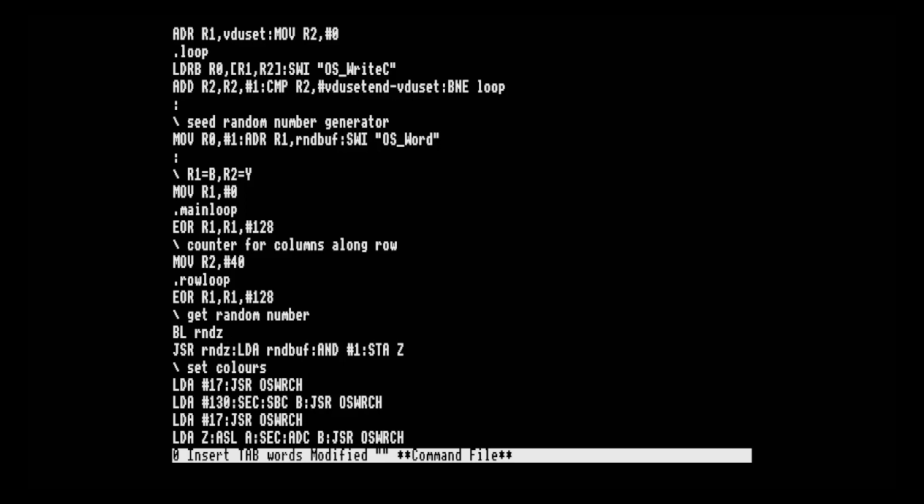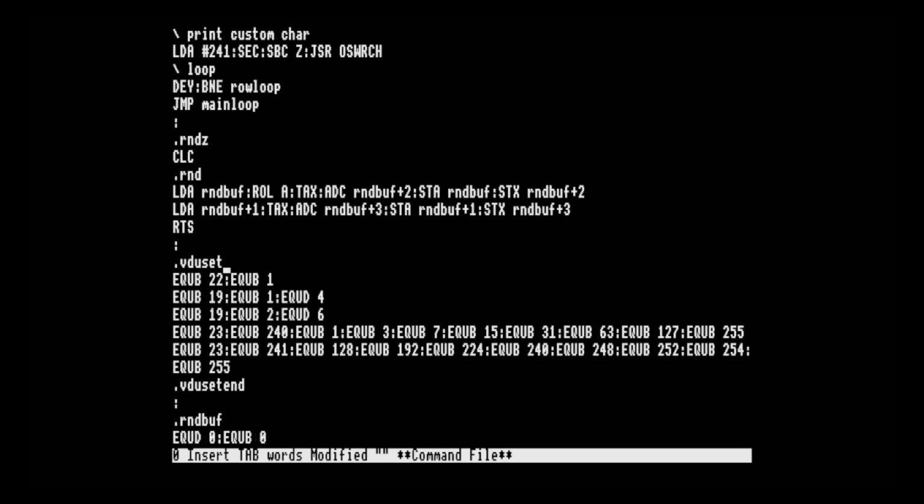Now we'll go on down to that part of the code, and we'll gradually convert that into ARM down here. Now this is a bit of a horrible mess, the way I'm going to convert this, and the reason is because this linear feedback shift register function assumes that all the operations performed on it are using 8-bit registers, and things nicely all sort of roll into carry bits and things like that. But on the ARM, because all the registers are 32-bit, we have a little bit of shenanigans involved in sort of moving things around and getting the right bits to end up in the carry bits for adds that come on later on.